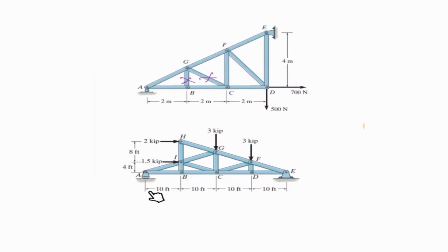And the last example here, let's try to figure out what is happening here. A, external forces. B, 3 links. One of them is perpendicular to the other ones, then we have a zero force member. Point C has 5 links, cannot have any zero force member. Point D gives us a zero force member. Point E has external forces. Point F, one of the links is already gone, the other one can be a zero force member.